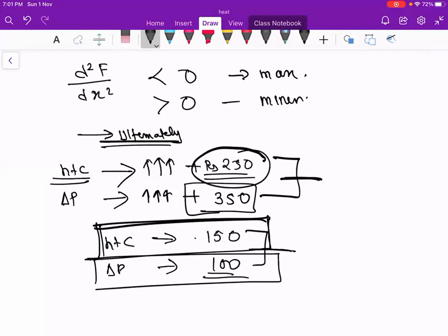Same thing, if you have heard in the distillation column: if you increase the reflux ratio, what is going to happen? The number of trays is going to decrease, but the load on the condenser and reboiler will increase. That is why we say the optimum value will be 1.2 to 1.5. This will come in the mass transfer subject. In absorption also, the optimum ratio is 1.2 to 1.5. Those who are in final year have heard of the optimum value of absorption and of distillation.